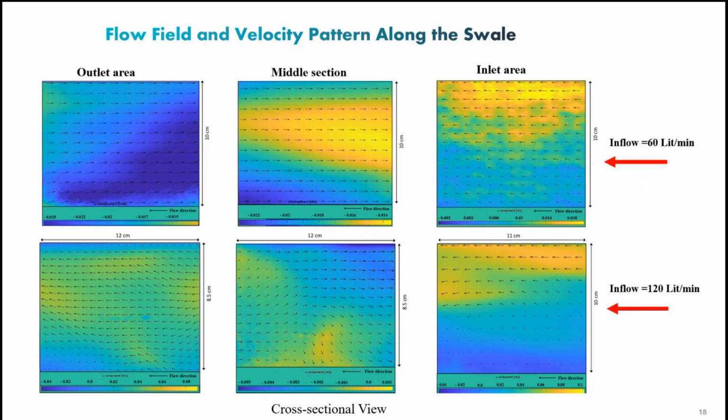But for the low flow, flow is going downstream, hitting the downstream weir, and moving back, bringing the sediment to upstream. So it's adding more residence time and improving the efficiency, but at the same time the turbidity is increasing because the sediment is being picked up from the bed and added to the turbidity of the water. Next slide, please.